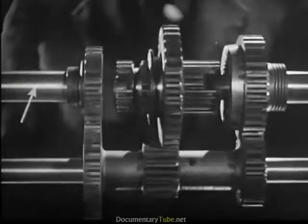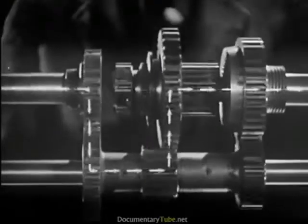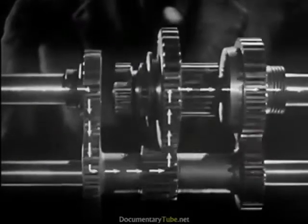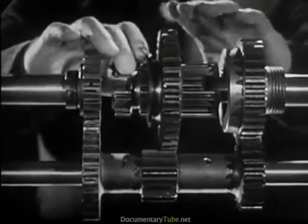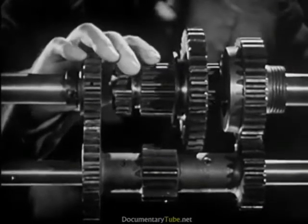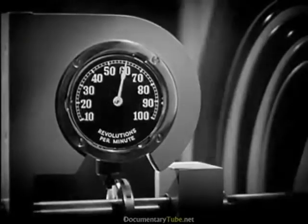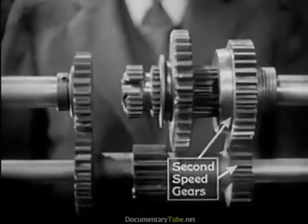Power is going through these gears in the transmission. After we've started the car rolling, we want fast pickup. So we shift into second by sliding the sleeve backward to mesh with this gear on the shaft to the rear wheels. The wheel is now turning at 60 revolutions a minute, and the power flows through these gears.